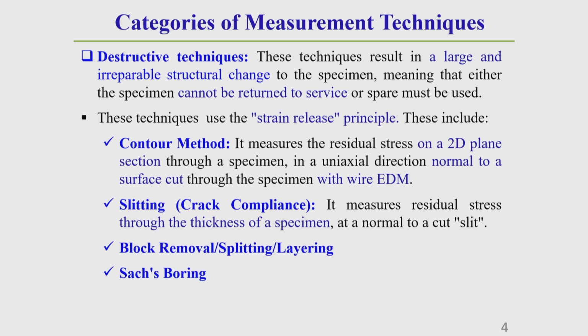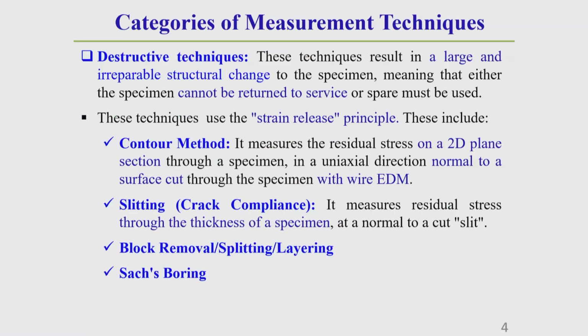This destructive technique is especially based on the strain release principle. What does strain release principle mean? I have told you that residual stress is locked-in elastic strain. The residual stress is generated due to locked-in elastic strain. This you should keep in mind. So, residual stress is an elastic type of stress. That is why once we remove that locking, it is released. Understand what I am telling?